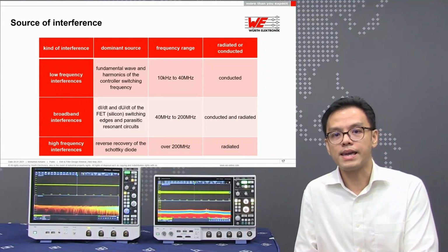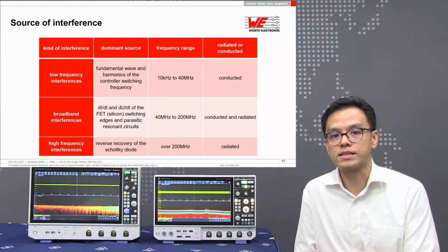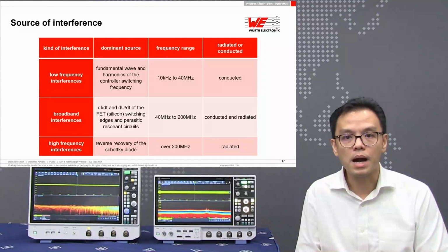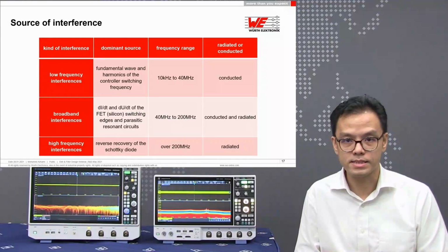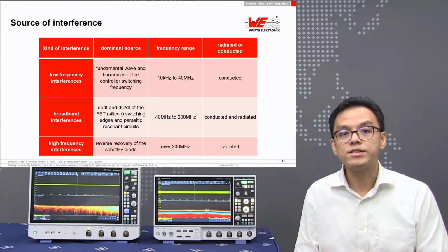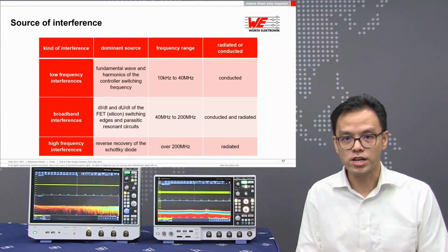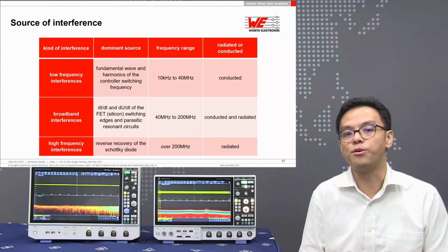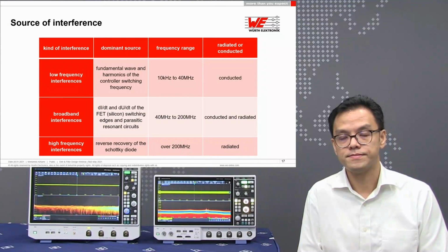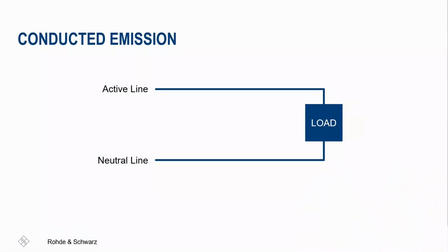EMC filter design emphasizes conducted emissions because they are more accessible for lab testing, especially when related to power circuits, which often require design adjustments and impact a broader footprint. Conducted emissions involve noise traveling through the main circuits, particularly in power circuits. The two main noise types are common mode and differential mode noise.